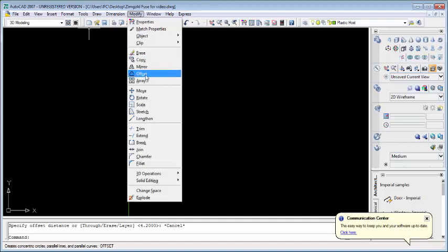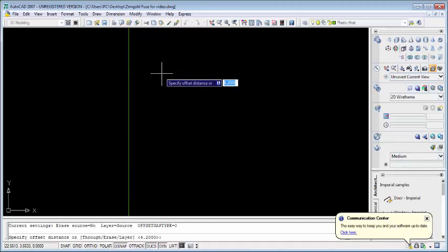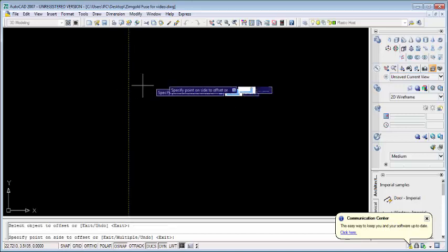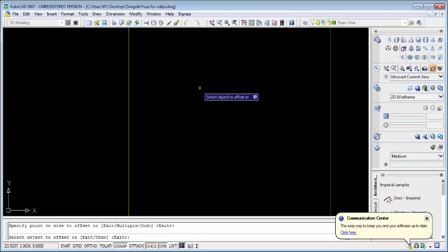This is the shape of offset. It's still the same thing. Select offset. It's asking you where do you want to offset to. I say I want to offset to 4.6 cm. Click enter and select the line. Select to the right hand side.